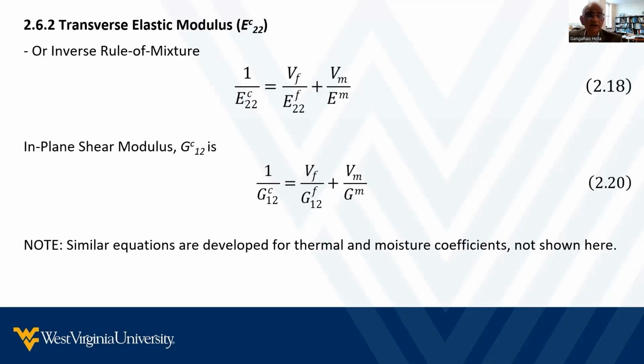And this slide develops a derivation for transverse elastic modulus. To find the appropriate transverse elastic modulus of a composite, meaning the modulus perpendicular to the longitudinal modulus as given earlier, transverse stress is applied by idealizing materials as rectangular boxes as we did before.